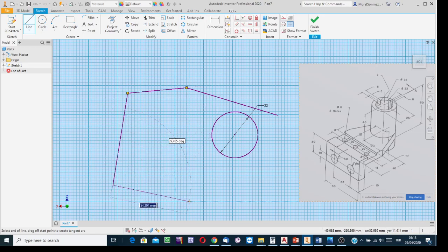One more line. While creating the boundary lines or the necessary lines for having the sketch in the end, avoid having a dotted line between the cursor and the characteristic point of the already drafted ones.